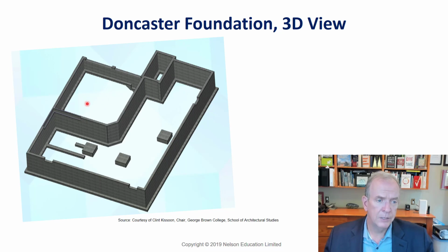Now, this may or may not be true. If you're building one house, this would be absolutely true. If you're building in a subdivision, you might be excavating for 7 houses in a row. It's usually easier just to excavate them all at the same depth and fill this back in later on, rather than have this at one height and this at another height. But if you're doing one house, it's easier to excavate at the different depths and not excavate out anything more than you need to excavate. So different practices depending on whether you're building a row of houses or whether you're building one house.